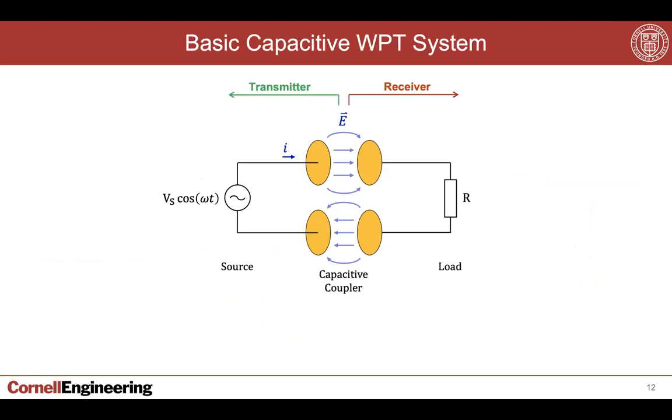All right, so what is a capacitive wireless power transfer system? At its heart, you have essentially a capacitive coupler, which has two portions. There's a forward path through which the displacement current goes from, in this case, the source towards the load, and then you have to have a return path. Each coupler comprises two metal plates separated by a distance. That's the air gap. That totally depends on your application. In the case of an automobile application, which is an area of my focus, that distance is at least 12 centimeters, which is the clearance of the vehicle from the road itself.